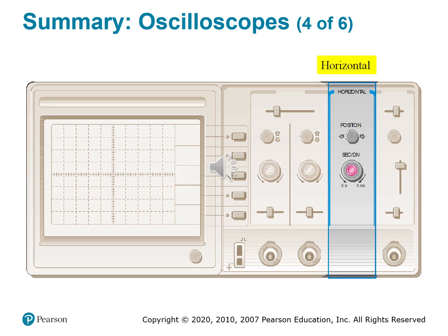Let's go ahead and break that down a little further. You have a knob that says seconds per division control, right? It's a time-based knob. This sets the horizontal scale measured in seconds per division. So for example, if I were to set the scope to 5 milliseconds per division, each horizontal grid box equals 5 milliseconds. If you turn it to 5 nanoseconds per division, you're zooming in to nanosecond level events, and changing this setting allows you to view an entire slow moving waveform, or to zoom in to analyze high-speed transients or glitches. And it's how you match the display to the speed of your signal.